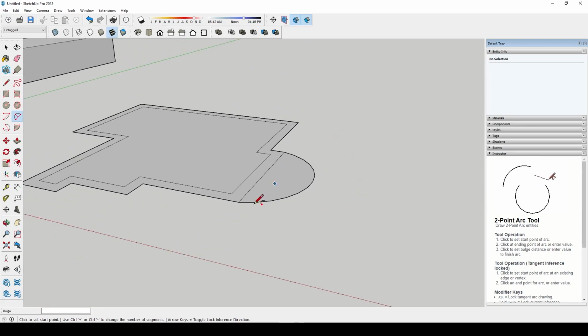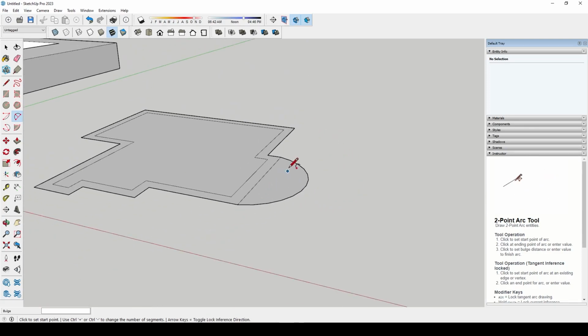By default it's making it very simple so that it runs really quickly, but we want the aesthetics to be looking good, and our house is not that massive that we need to worry about it. So if we hit A for arc again, it'll open up this sides dialog down the bottom here. And if instead of 12, we just start typing, that'll replace that. So I'm going to up that to 100, and then I do my arc again, and we'll notice it is a lot smoother around that edge there.